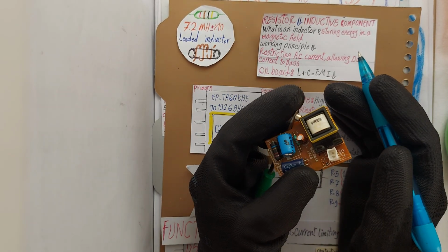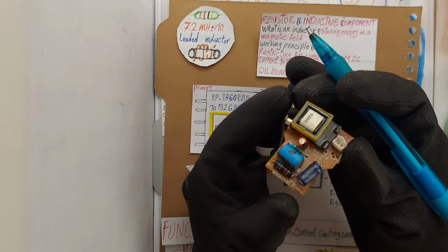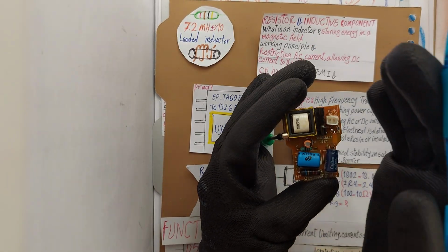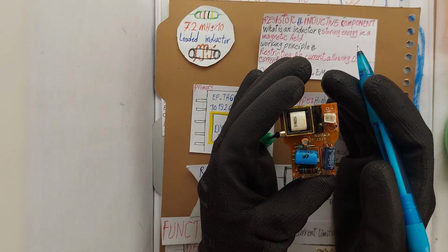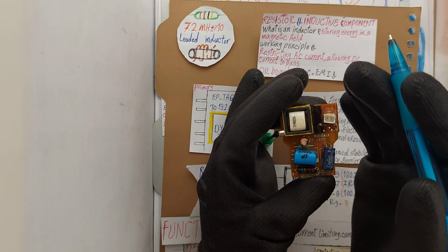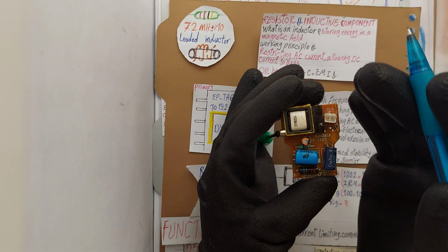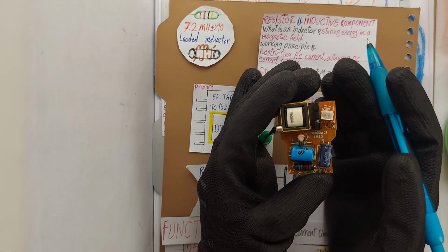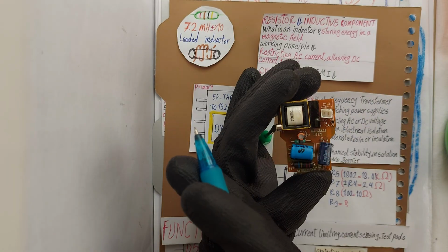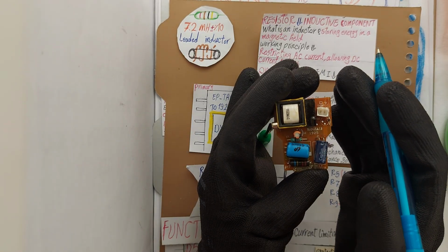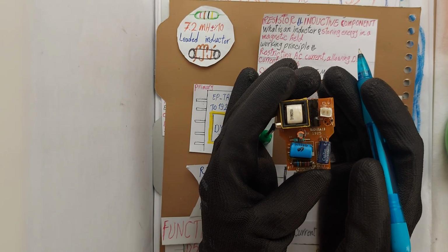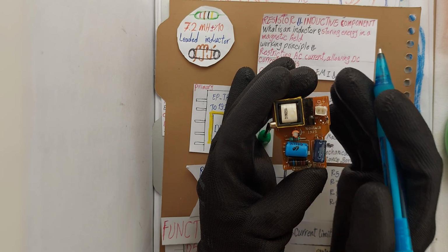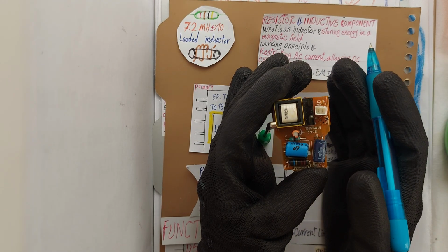Now, what's the transformer's role? In the charger, it converts high AC voltage from the input after rectification into a low pulsed DC voltage to provide the device's required energy. Then provides electrical isolation between the high voltage input and the USB output, ensuring device safety. Works with a switching transistor, usually nearby, and a control IC to regulate voltage and current.